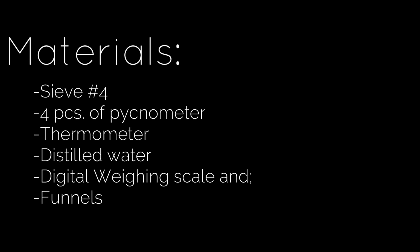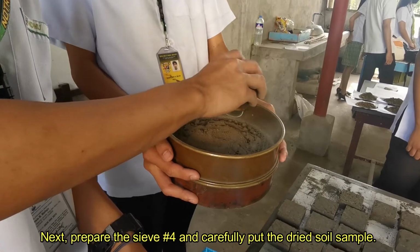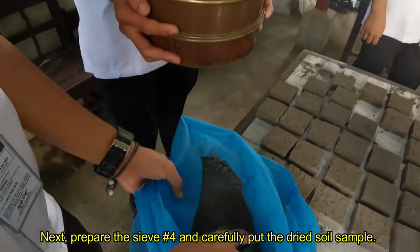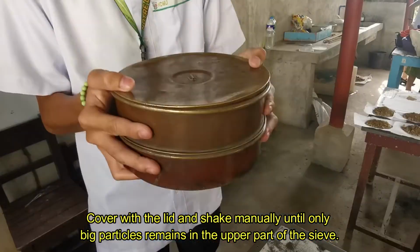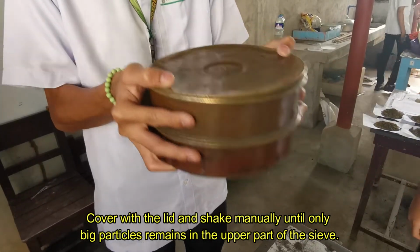In the laboratory, prepare all the materials needed to conduct the test. In determining the specific gravity, you'll be needing a sieve number 4, 4 pieces of pycnometer, a thermometer, distilled water, a weighing scale, and funnels. Next, prepare the sieve number 4 and carefully put in the dried soil sample. Cover with the lid and shake manually until only big particles remain in the upper part of the sieve.